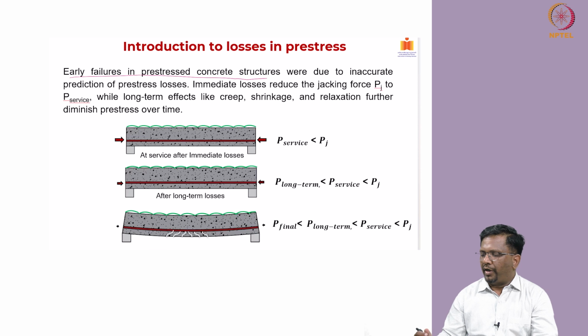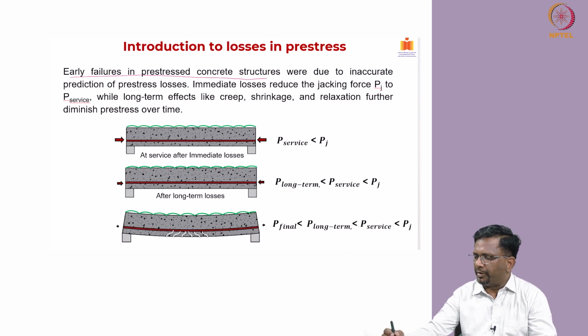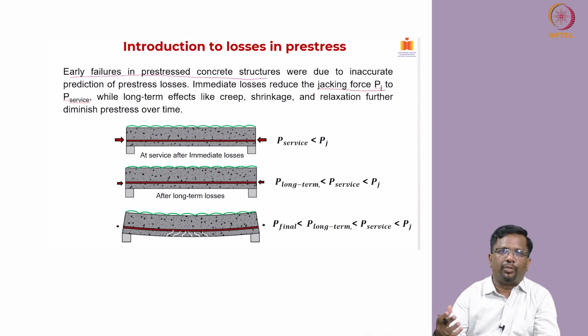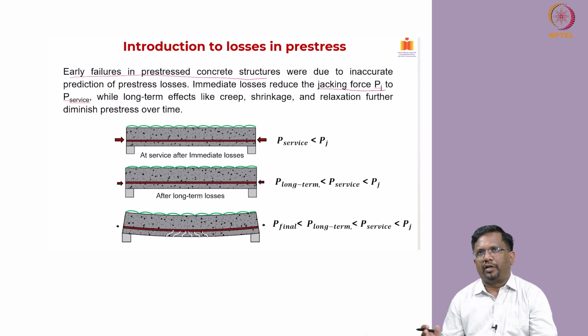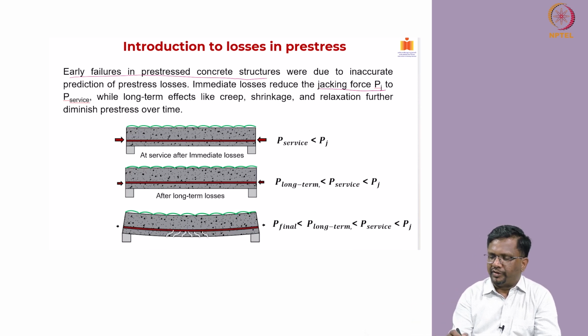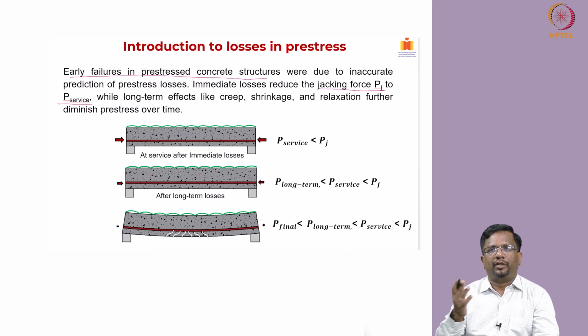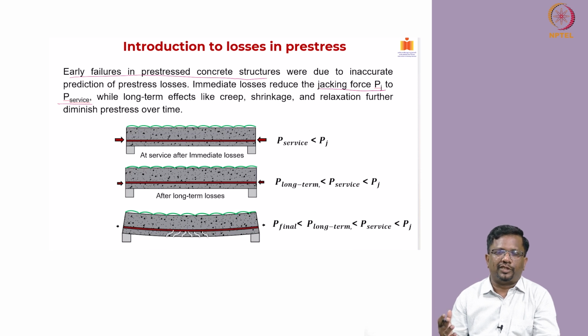Now, when you apply the prestressing force, typically the jacking force is the force that you actually apply initially on the prestressing cable. Then that will reduce to P service, which is the prestressing force that exists while the member is in the service stage, right. Depending upon whether you are looking at 1 year or 2 years or 3 years, the prestressing force existing in the member will differ, depending upon the time at which you are calculating it.